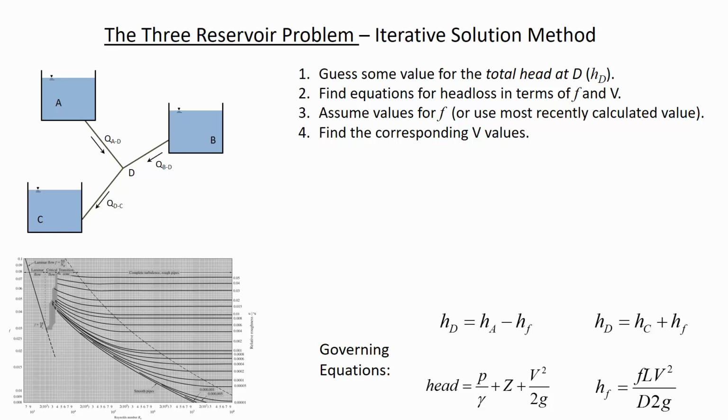I'm glad that you asked that question. That's an important question. And it turns out that the diameter doesn't have an effect because even if a tank is wide or narrow, down at a certain elevation, the pressure is the same because delta P is equal to delta H times gamma, which is the unit weight.